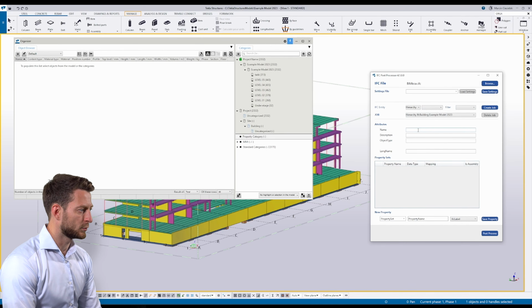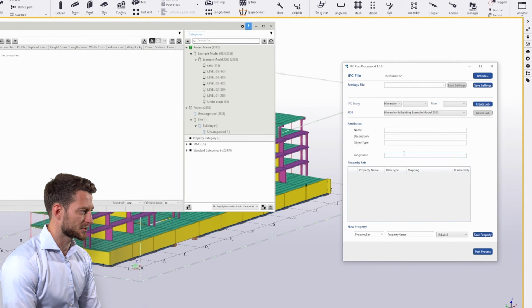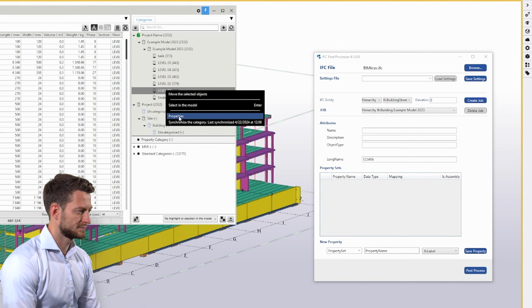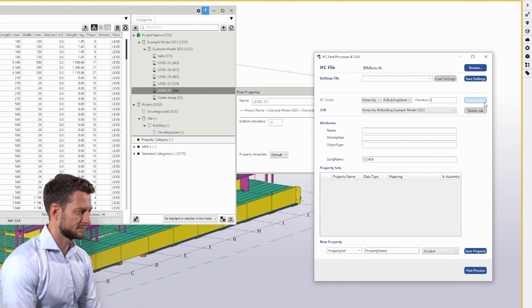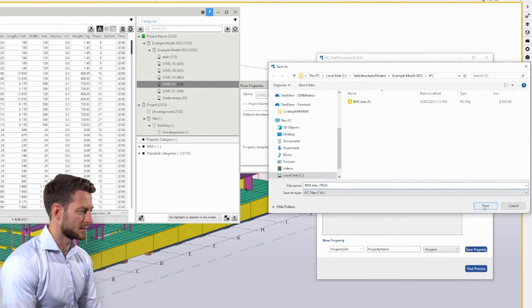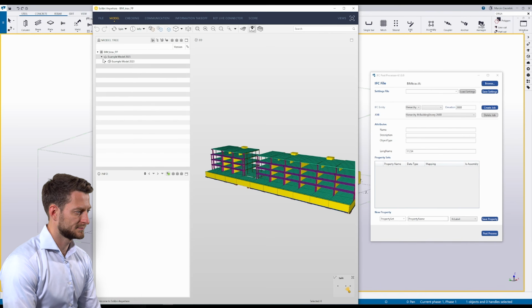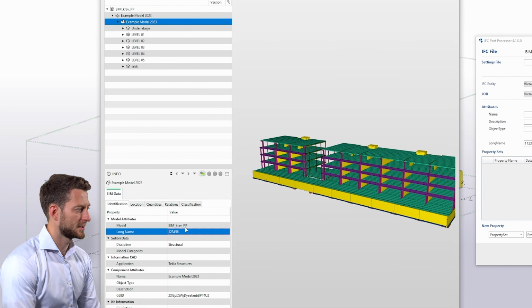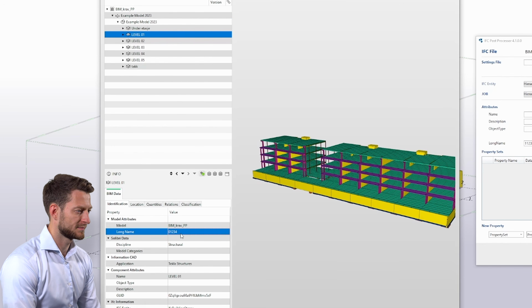To map the right floor for IFC building storey, instead of names, we need to use bottom elevation. Then add proper long name, and at the end, click the Post Process button up at the bottom. We can see that now both building and selected building floors have filled long names.